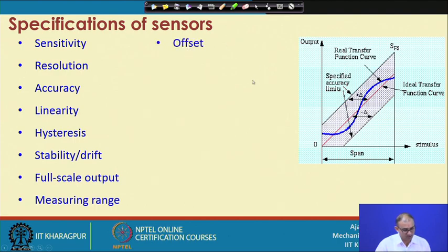Right. Then offset is important, because it is the location from which the measurement starts. So, those offsets should be accounted for when you do the final calculation of the actual forces. Response speed means that once you give a signal, after how many microseconds or milliseconds your sensor responds to that particular stimulus. That is important. The faster the response speed, the faster the sensitivity. That is directly related to the data acquisition system, that is, what type of system you are using for capturing all those signals.